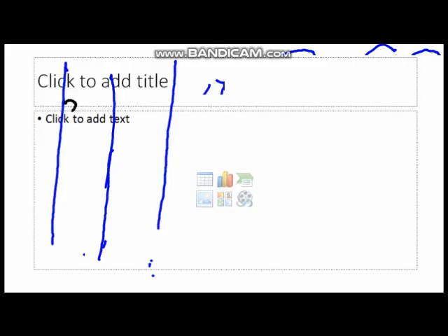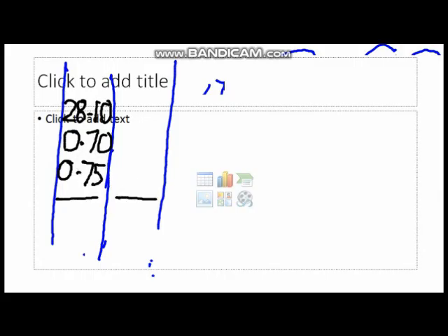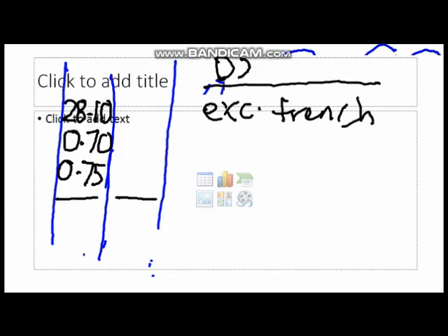So your dimension should be put in the second column, which is the mean girth just now. Then the width would be 700. So everything is now in meter. And your height of your trench should be 0.75. Then that is your excavation for trench. You need to check the code. It should be under D20. Okay. So try to check that in your SMM.